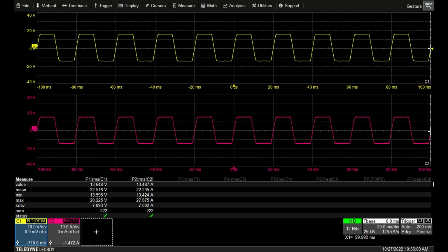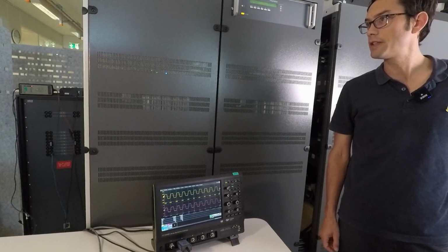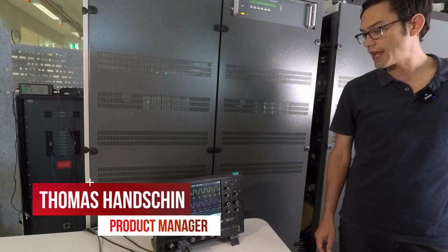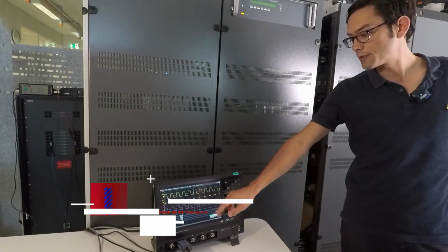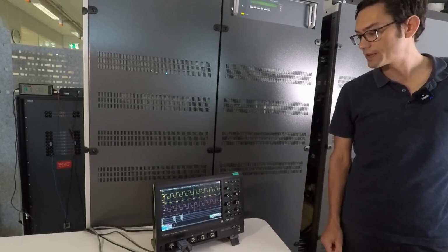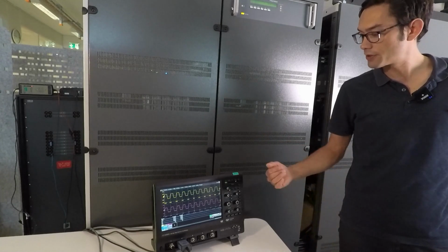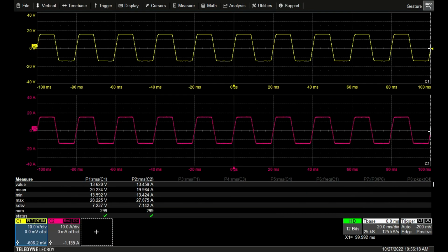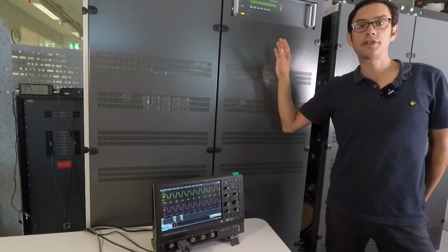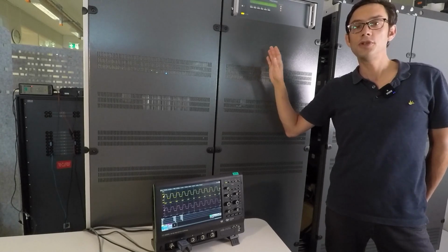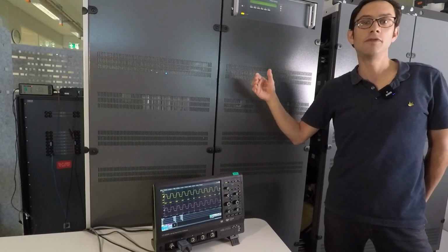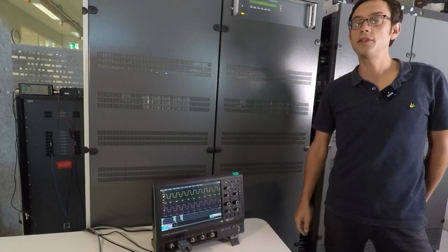So as you can see, it's a very, very fast current limiter at peak. So it really clips this 50 Hertz signal exactly at 10 amps, remains at 10 amps for some milliseconds, and once the voltage comes down and the current comes down, it goes back to the sine wave shape. So this is the peak current limiter in RMS. There are certain use cases for this, but usually in AC you use the RMS current limiter, and in DC you usually recommend to use the peak current limiter.